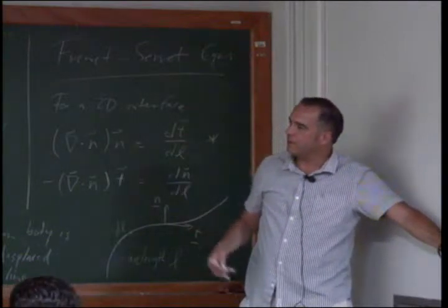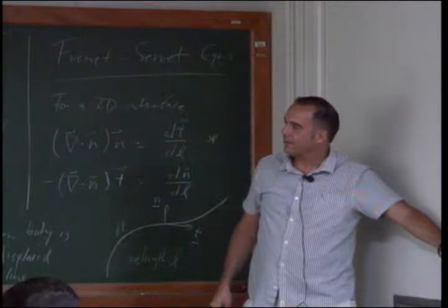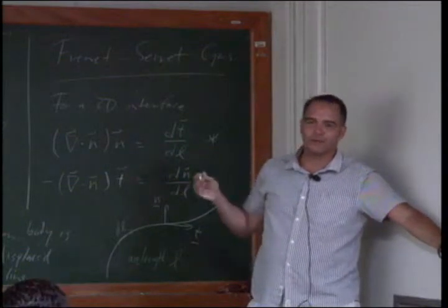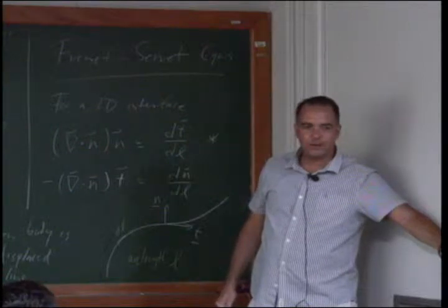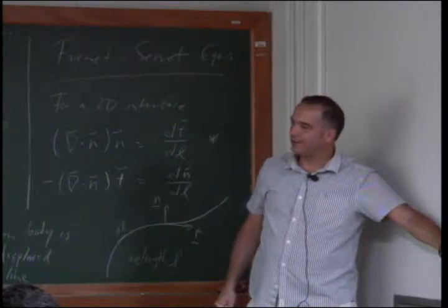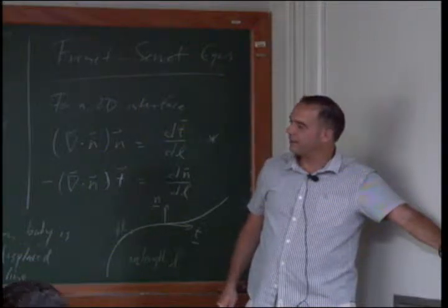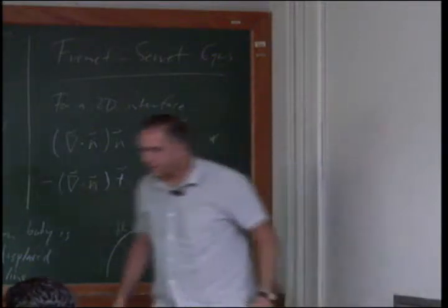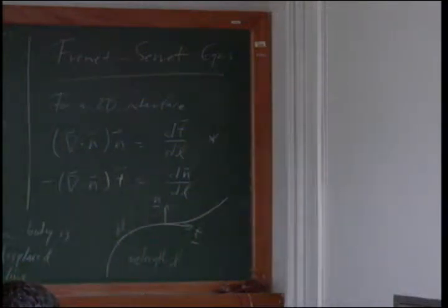So the nice thing about these surface tension problems is, when you look at any fluids problem, the first thing you ask is what's the Reynolds number? And then you decide whether inertia or viscosity is going to dominate. And then, if you're looking at an interfacial problem, you say how big are things relative to the capillary length? And that'll prescribe what's dominating the system, whether it's surface tension or gravity.